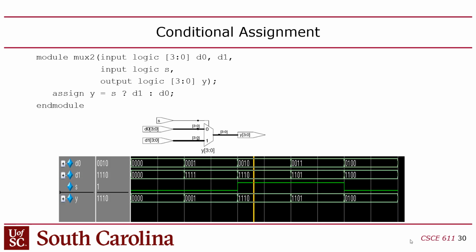So in lab 2, your goal is to create a 7-segment decoder, and you could do it with just one assign statement with this nested ternary. There's other ways to do it too, but that to me is the easiest way to do it. Just make sure that if you have a nested version of this, you have a catch-all else on the end, and I'll show you an example of that too in a minute.